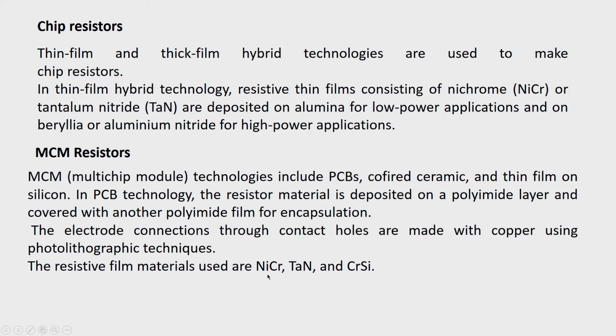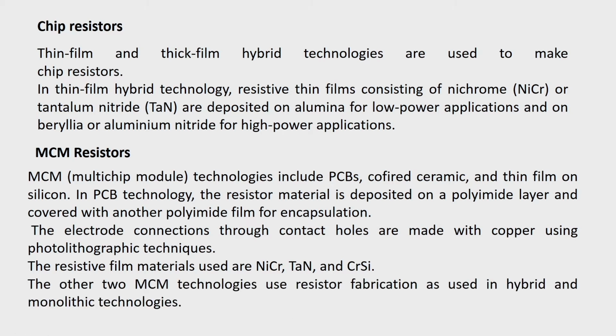The resistive film materials used are, as we have already mentioned, nichrome or nickel chromium, or tantalum nitride or TaN, and chromium silicon. The other two MCM technologies use resistor fabrication as used in hybrid and monolithic technologies.